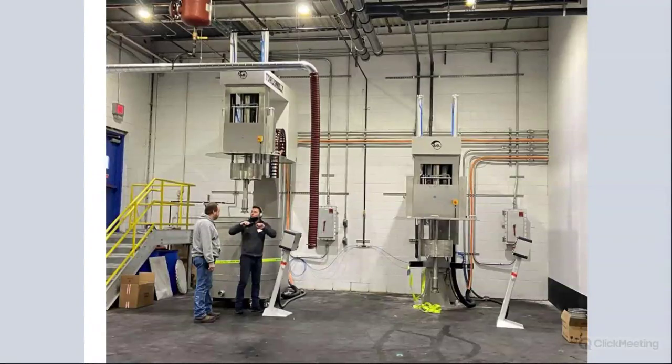After that, he pushes a button on the control panel, and the basket will come down, travel down along the shaft, and now you're turning this into a basket mill. So he never has to move the container to a different system. Everything can be done in one location, pre-dispersing, adding your materials, and then milling, which is a huge advantage over some existing production units where you have to move from dissolver over to a basket mill and then move the container again. So here everything can be done with one machine in one location.